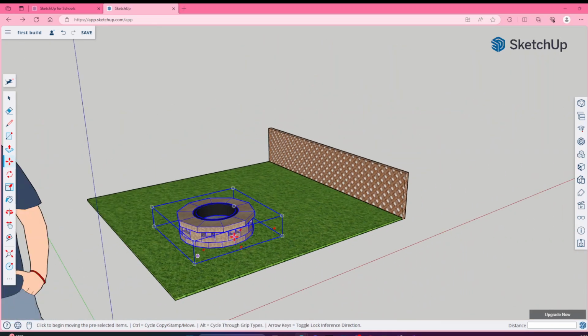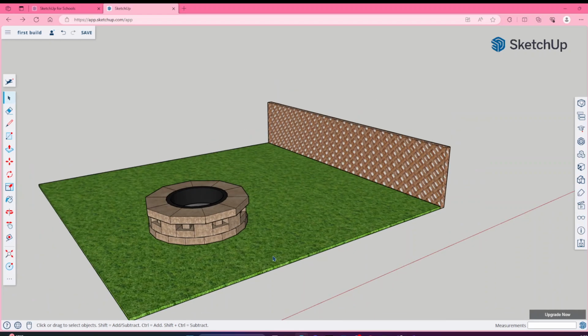So when you use these 3D Warehouse components, they sometimes can be edited, they can be scaled, and they can be moved around and positioned accordingly. So it'll just be a little bit of experimentation to have a look at what's in there. Are there useful components for you? But remember the triple click, make component, and then when you apply your materials or textures, it will apply it to the entire component.